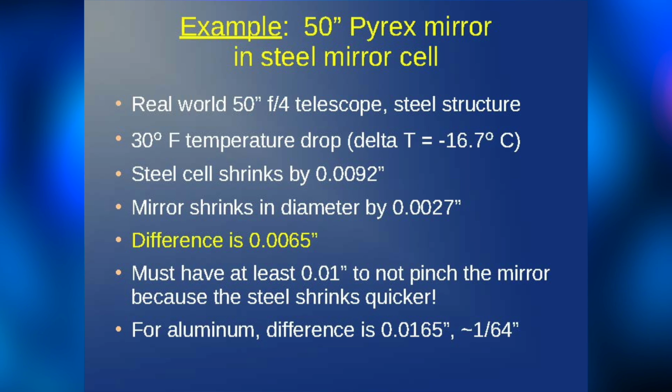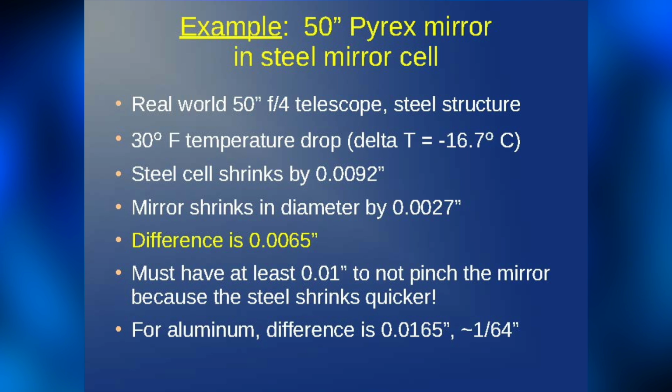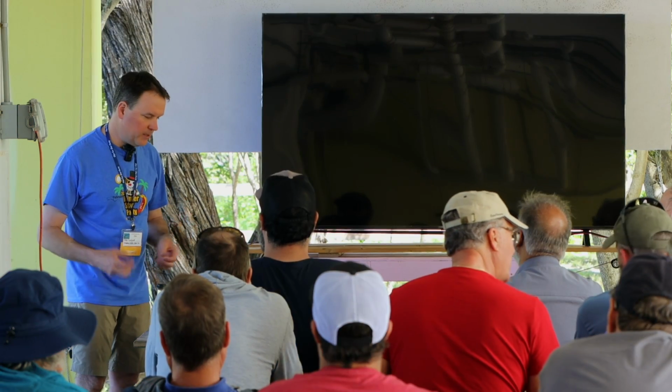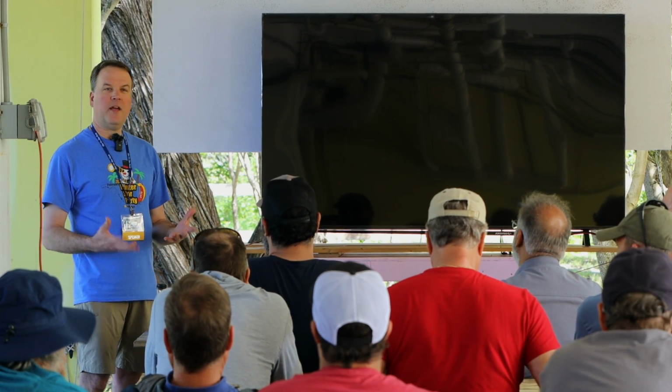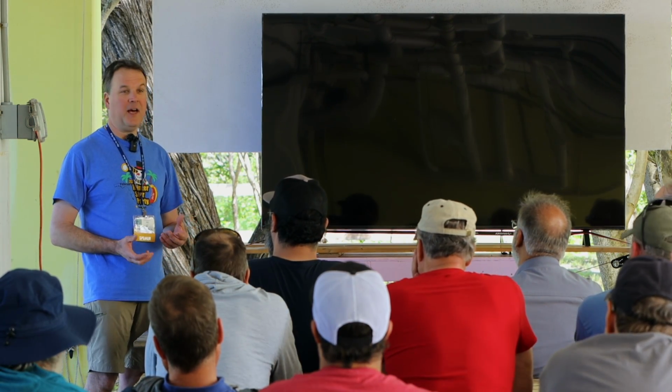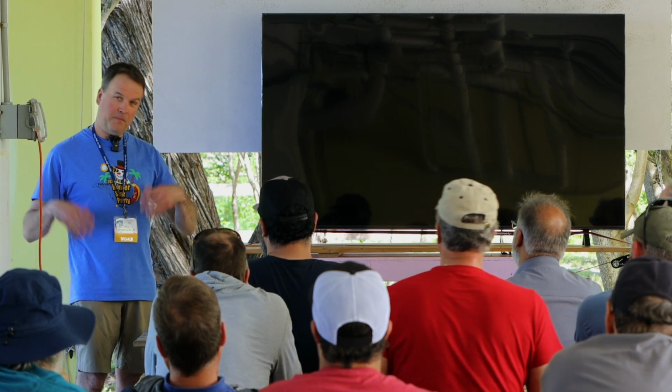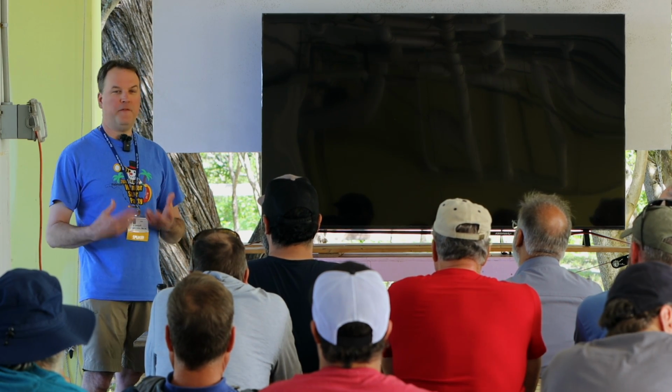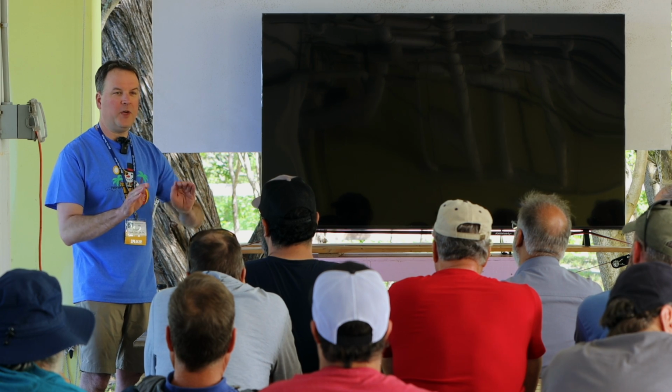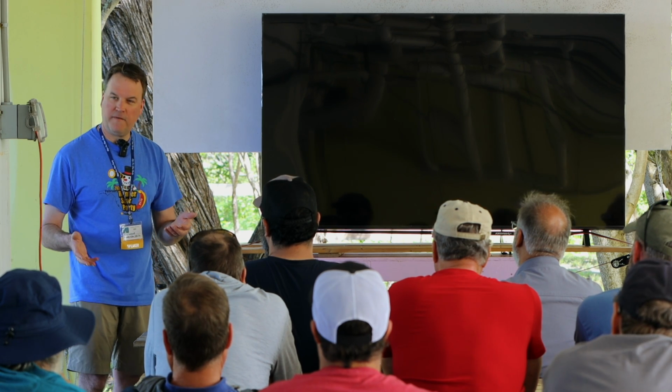Then think about if you're gluing a mirror to something. What do you need to pay attention to? How much they both shrink and how much the glue can flex. So generally I recommend not gluing mirrors because you can have a lot of problems, and partly again that's selfish. But if you know what you're doing and you do it in a way that the glue can actually flex, it can actually work fairly well.